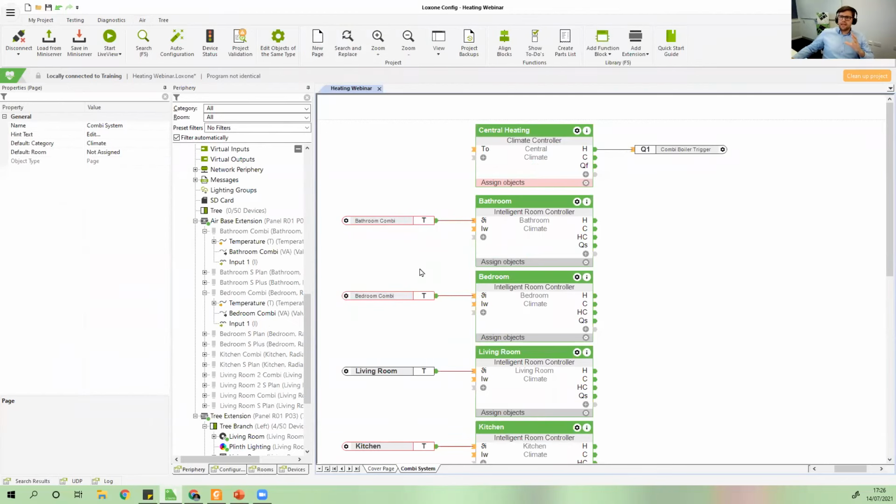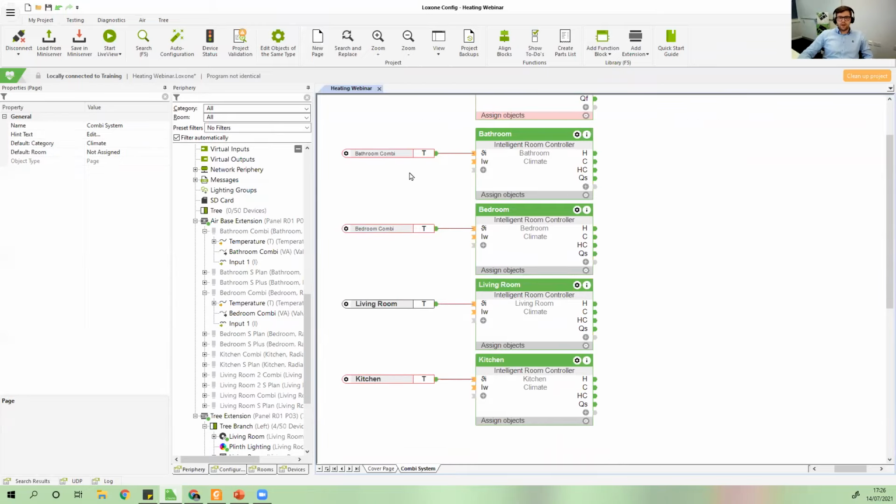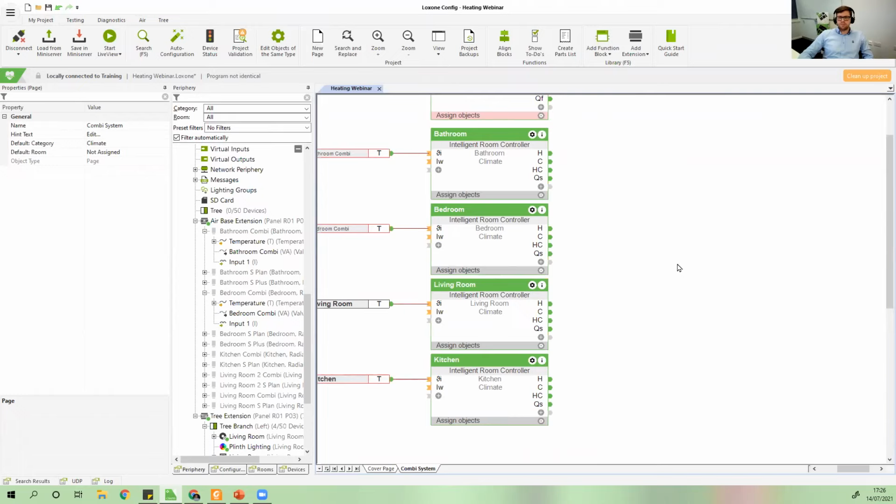In less commonly used rooms, that can be a good way of getting a temperature reading without going to the expense of adding in an additional sensor or an additional device if you have nothing else in that room. Just make sure that it is a fairly modern radiator that isn't going to throw its heat out left, right, and center, and massively throw the heat of that temperature sensor out. But otherwise, there we have our temperature inputs.